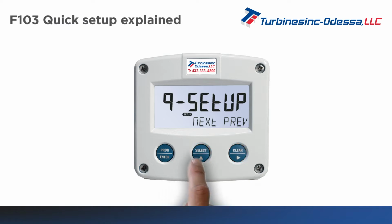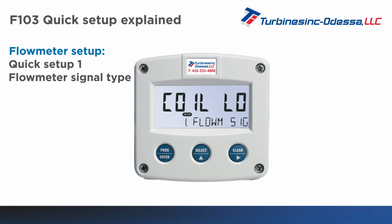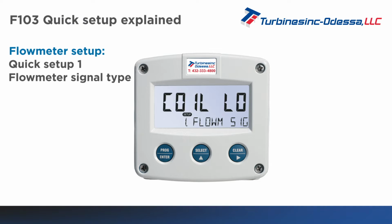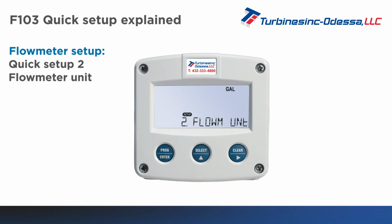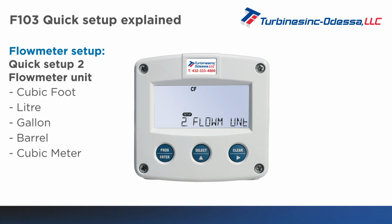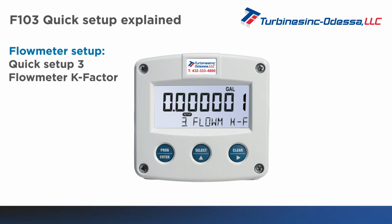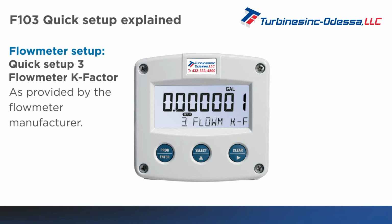Flow meter setup. Quick Setup 1. Here you can set the flow meter signal type, coil low, coil high, or isolated active pulse signal. Quick Setup 2. Here you can set the calibrated measuring unit for the flow meter, cubic foot, liter, gallon, barrel, or cubic meter. Quick Setup 3. Here you can enter the K-factor for your flow meter as provided by the flow meter manufacturer.